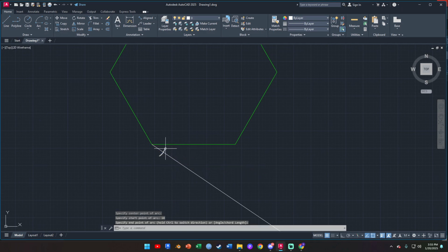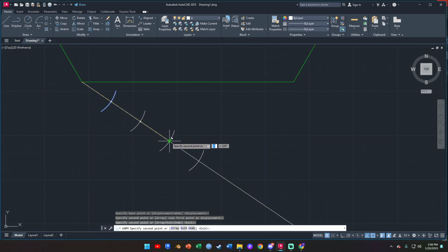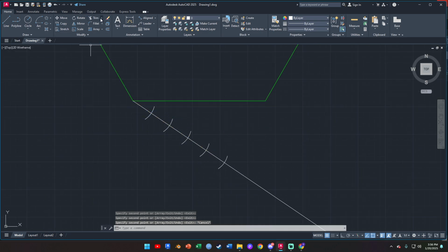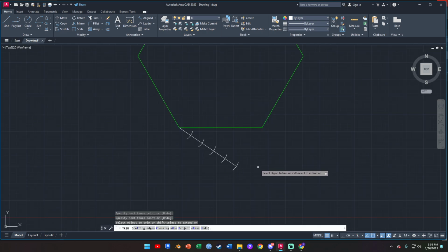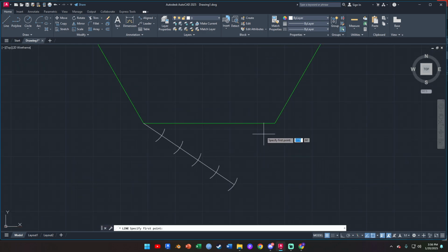So you're going to be scribing arcs of equal measurement until you have 5 arcs here. Right, so all of these things we actually did last term. The only difference was that you did it using a pentagon, right?